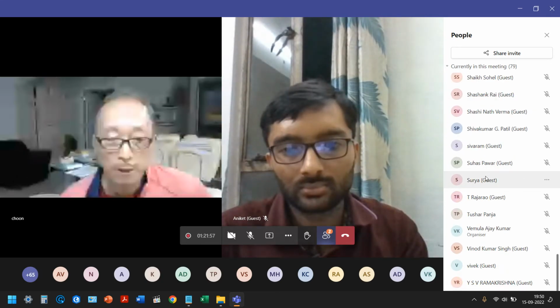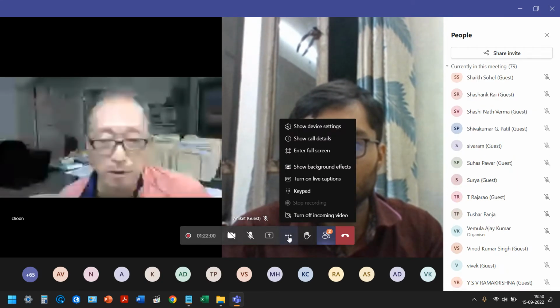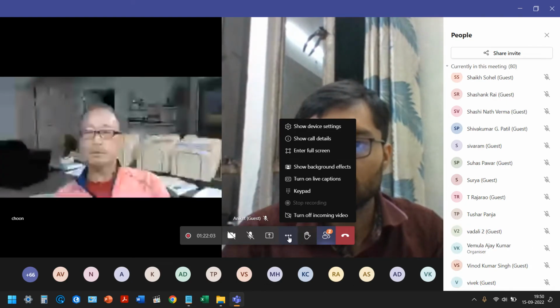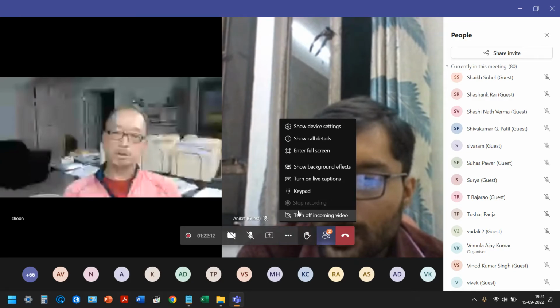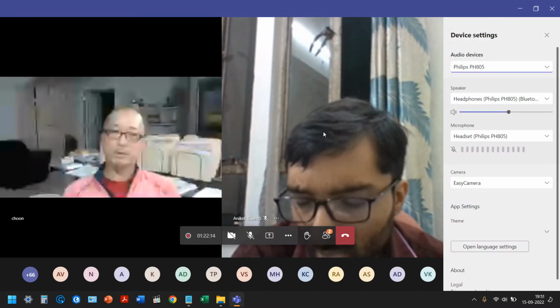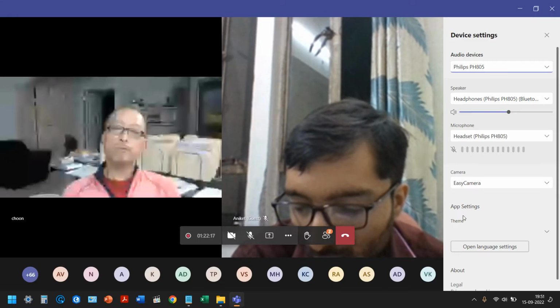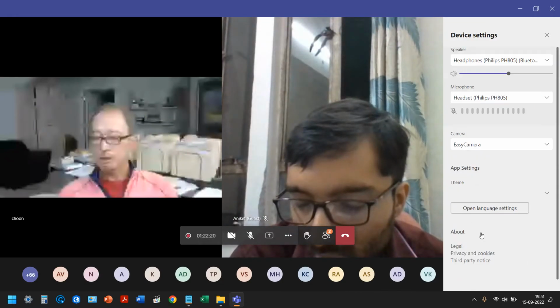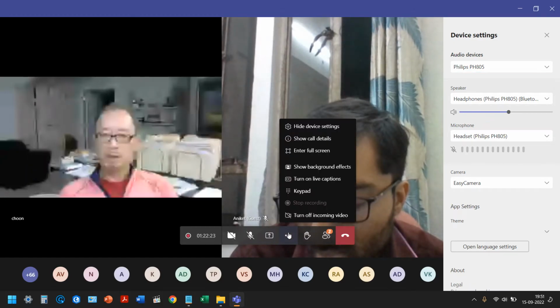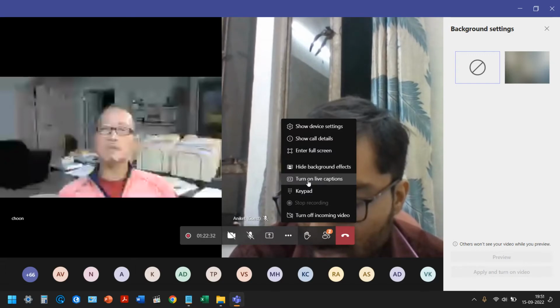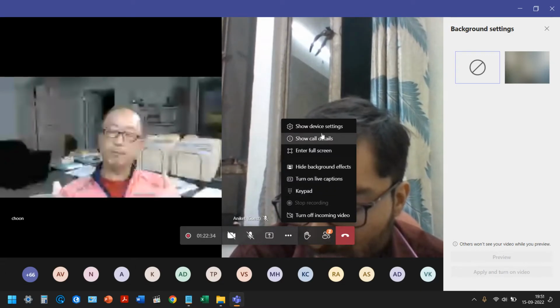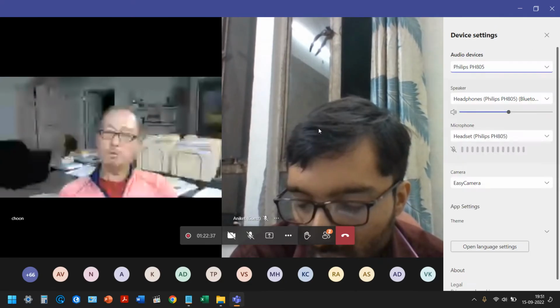And then the next question is, what is the role of source offset and movement step for a successful survey? Okay, so source offset is important. In other words, if your shot point is too close to your receiver array, then several geophones very close to your shot point will not have surface waves recorded, because for surface wave generation you need a certain distance away. Otherwise, the surface waves are not generated, and the near offset geophones will not contain useful signal.